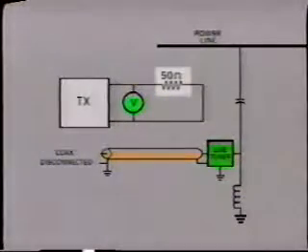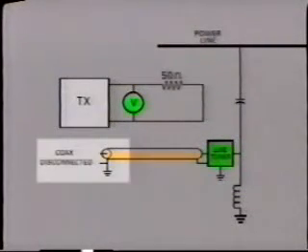Of course, here we're presenting just a general outline of tests to be performed. In practice, you'll have many more fine adjustments to take care of. Make sure that you follow each step laid down in your specific equipment instruction manual. And don't forget to remove the dummy load and reconnect the coaxial when the tests are completed. Now let's look at the other half of the carrier equipment, the receiver.